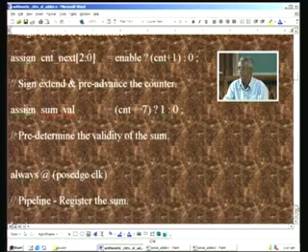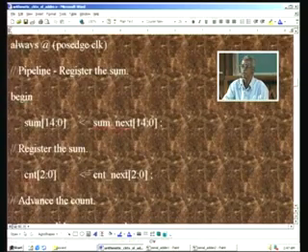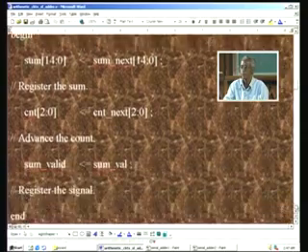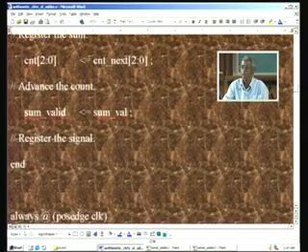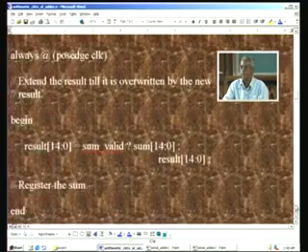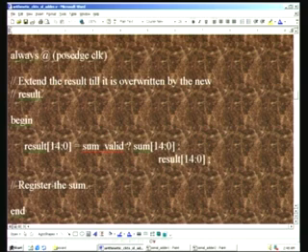And next is the always block on the positive edge of the clock, where we take the final sum and merely assign it here. This is what is already computed, and we merely assign it to the final output, which is sum. Similarly, the count next, which was pre-incremented earlier, is assigned to this count register, and this is for advancing the count. And naturally the sum valid which was assigned earlier is actually output to the register.